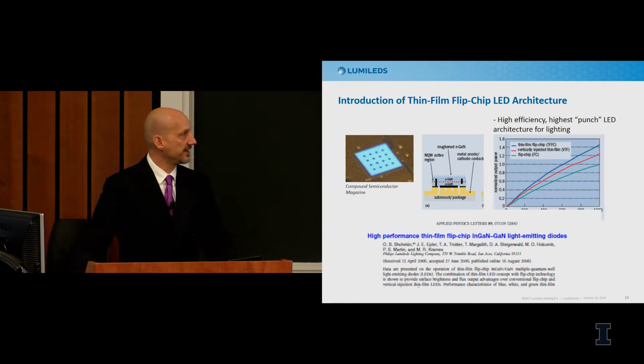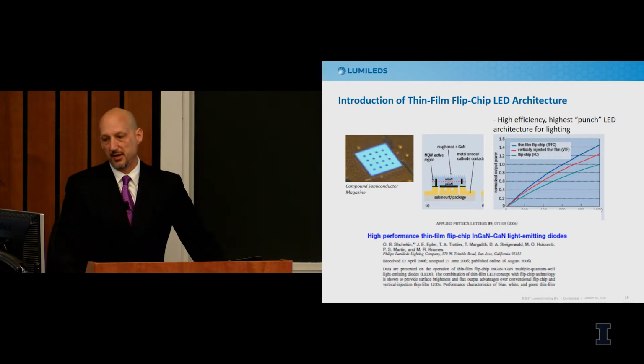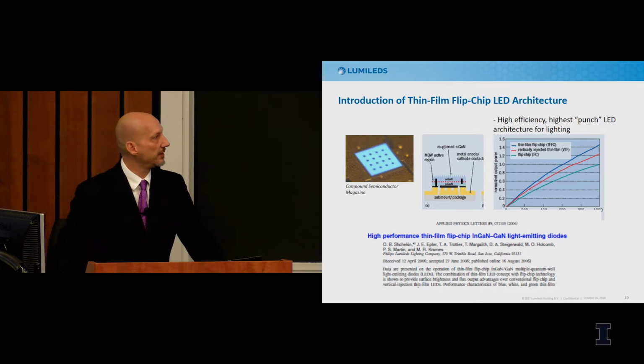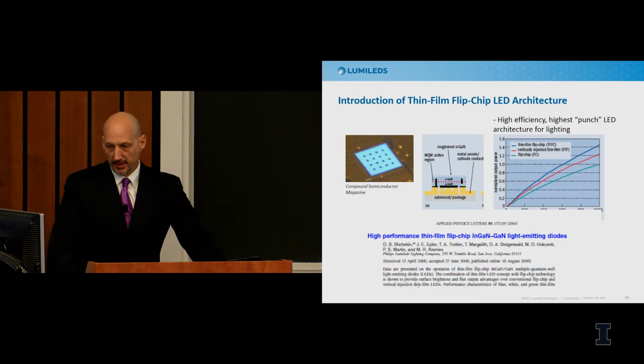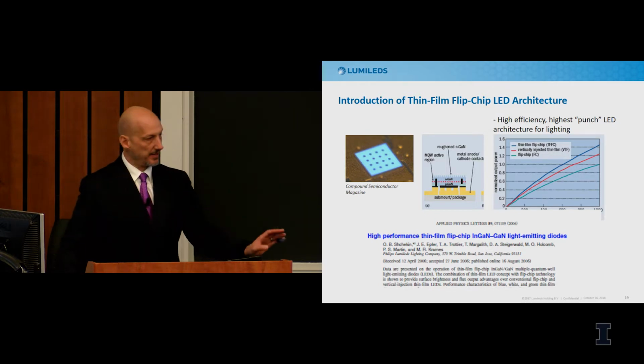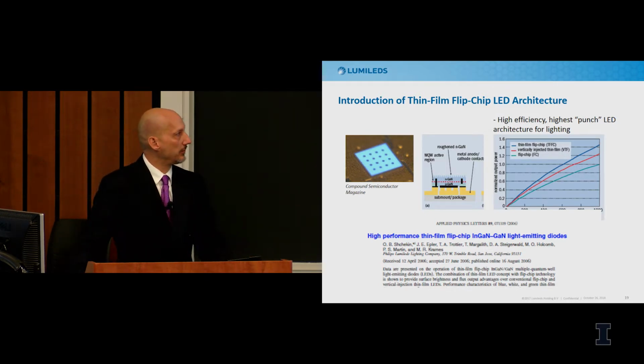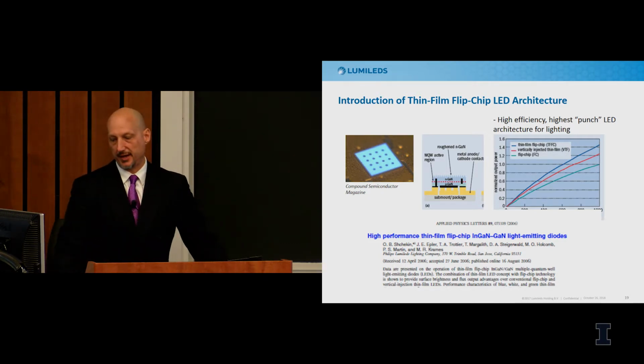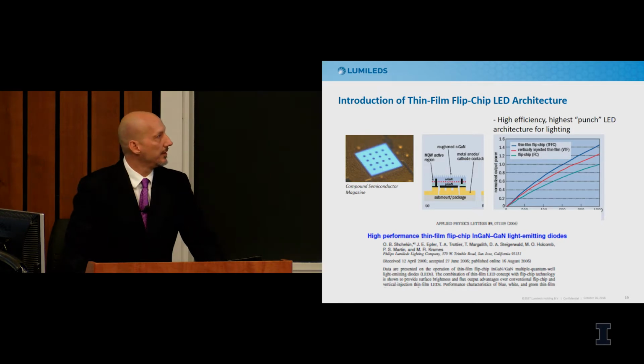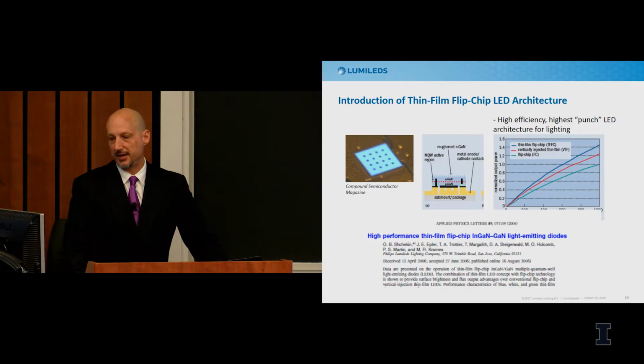There's lots of technology that goes into how to manage light extraction, not just from things like roughening, but even from very sophisticated physics around how to manage the interaction between a dipole within the active region and the light emission. Lots of device physics here, as well as managing the heat and other mechanical properties. So these are very complicated devices, even though you might think of them just as a PN junction. They're not.